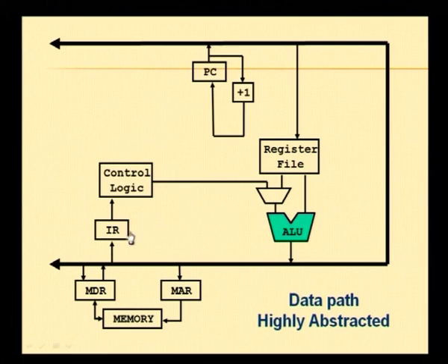So, fetch basically will mean taking from the PC, storing the value into the memory address register, that is giving the address to the memory, then taking the data which is fetched from memory, which actually is the instruction in this case. This instruction will now be stored in the instruction register. So, this is our first step or the fetch step.